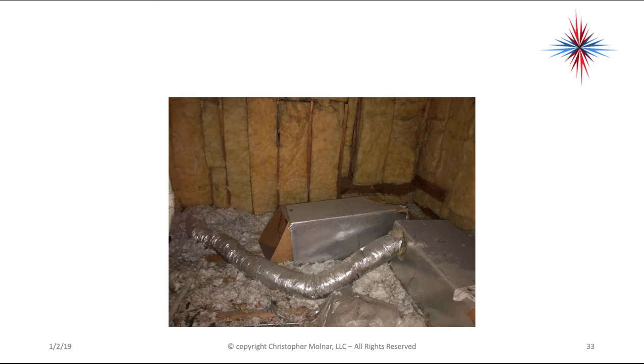Okay, now this is my plenum. Again, my furnace is over here to the right, so I transition to that plenum. This one, nothing's connected to it, so we don't worry about that. Okay, but see this one duct takeoff coming off that end of that plenum. I have a kink here, I have some restrictions here, and then I go into a grill right over here. That is very loose. Someone took a 25-foot piece of flex right out of a box and just attached it on both ends.